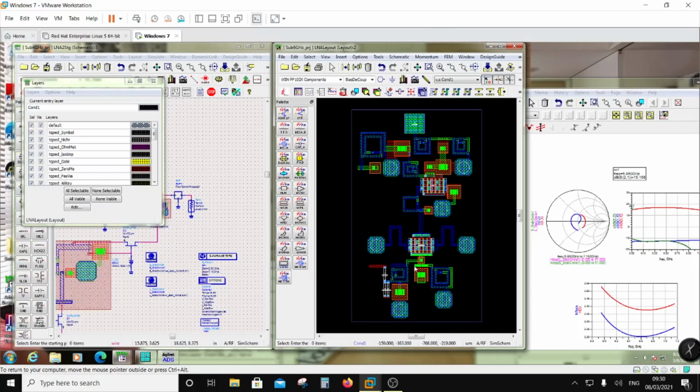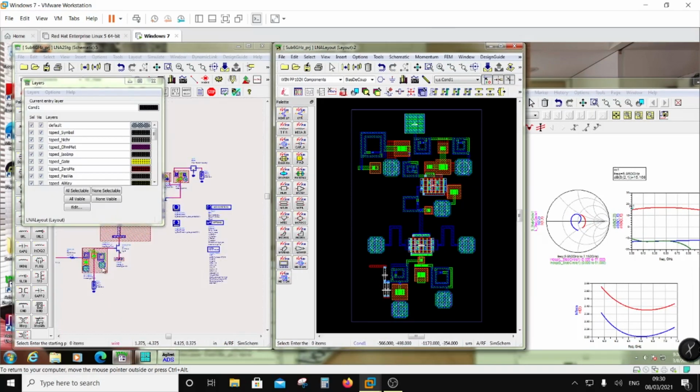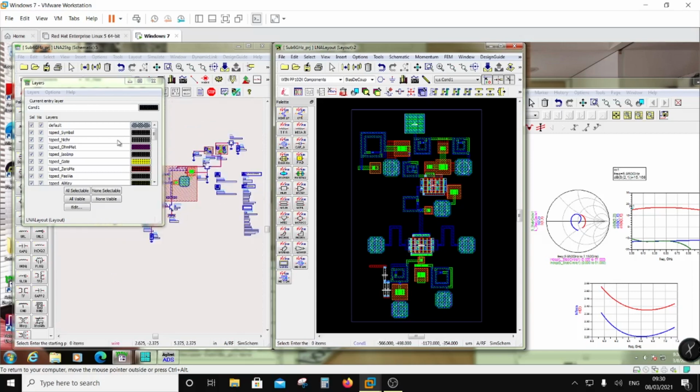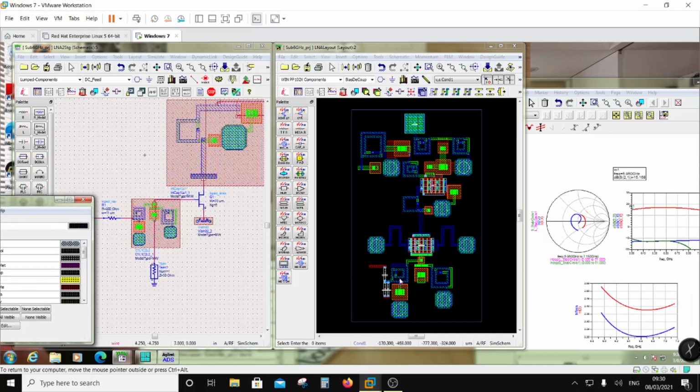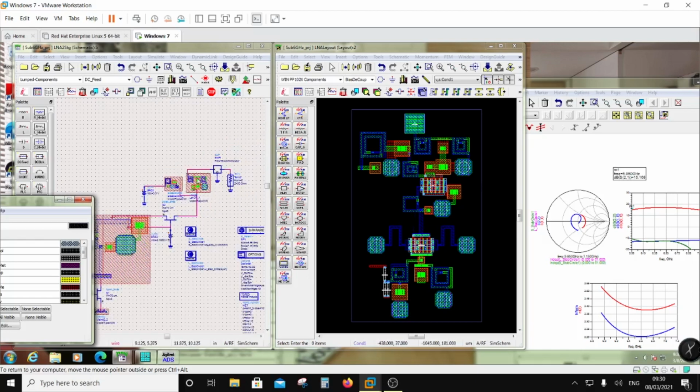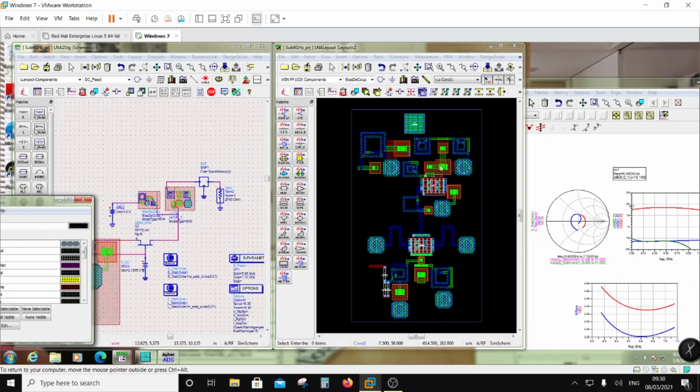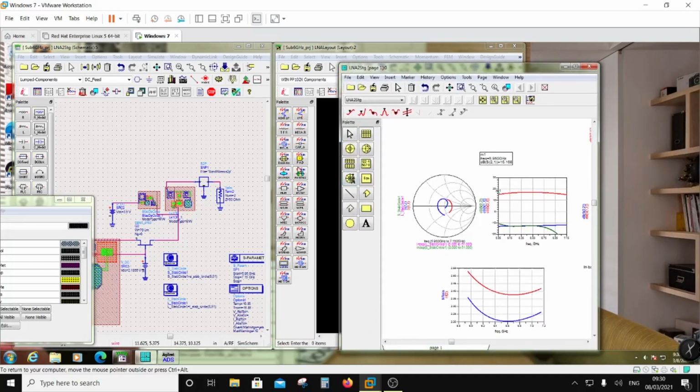There's an input stage which matches over here. That's your input stage here and here. That's your interstage over here and here. And that's your output match, and that's your bias decoupling. So that way I have covered the entire layout and layout EM cosim.